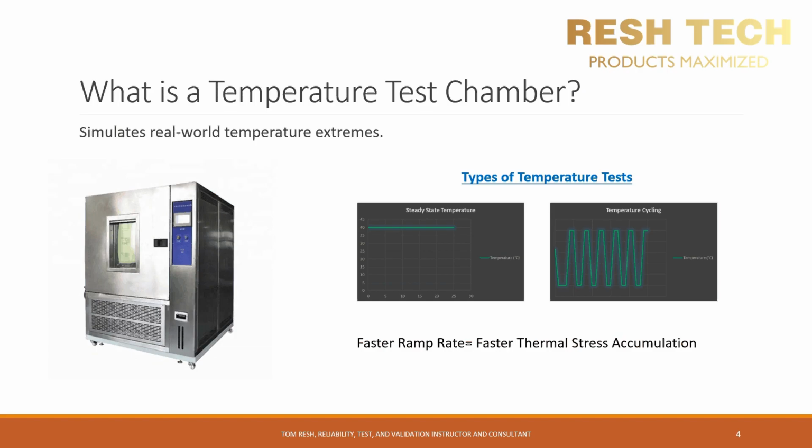A quick note, with temperature tests, you will often hear terms such as operational or non-operational temperature tests. What is meant by this is that the temperature profile is either run with the product or system in operating conditions, or with the product powered off. For example, a mission temperature profile would have your system or product operating as if it were being used by a customer under temperature extremes. If you're running a storage temperature test, the system or product would be powered off and in a non-operational state, as it would be in storage in a warehouse or customer location until it is used.